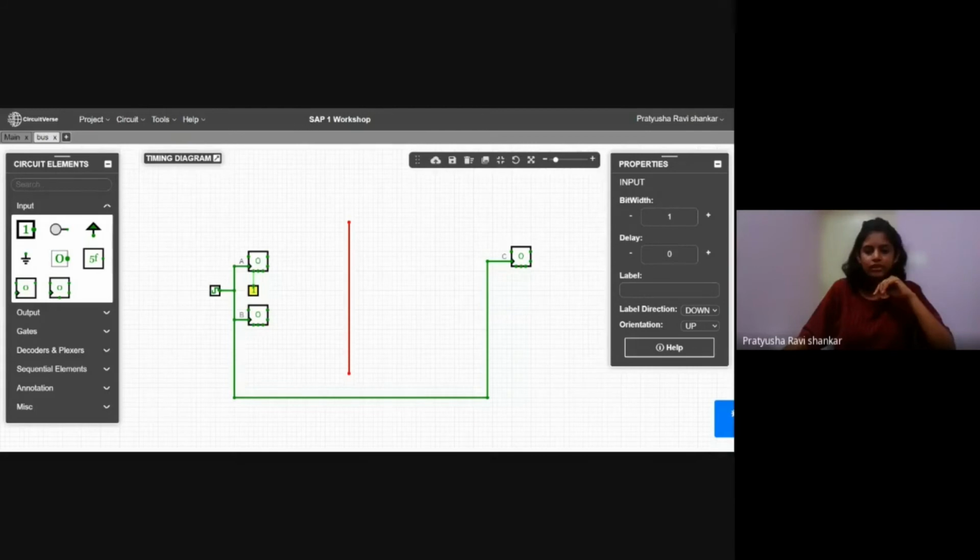Okay, let me give a quick overview. It's called asynchronous because your sequential elements all depend on either the rising edge or the level of the clock, right? But what asynchronous means is that even when the clock is not in a rising or falling edge, as soon as you set it to 0, the register immediately, without any delay, gets set to 0. If it were a synchronous reset, even if your input were 1, it would wait, being clock dependent, till your clock falls from 1 to 0 and then make the register 0. So that might be handy for you to know.